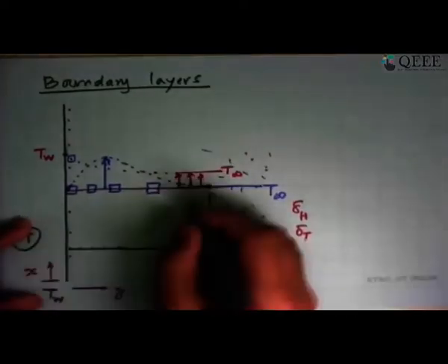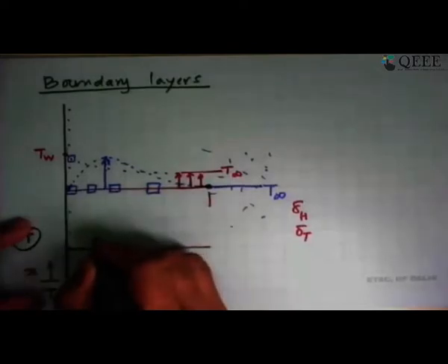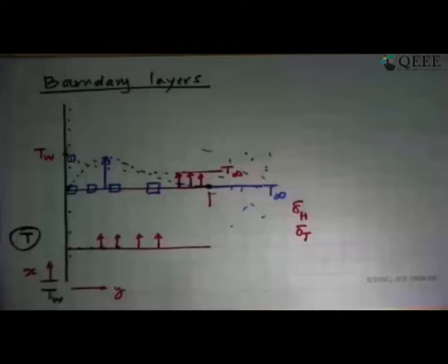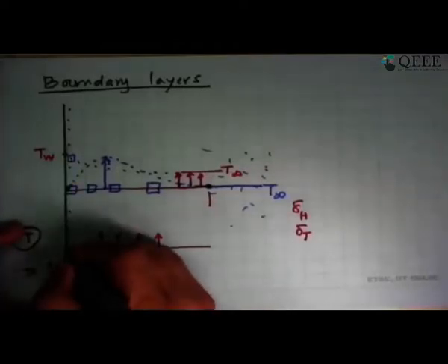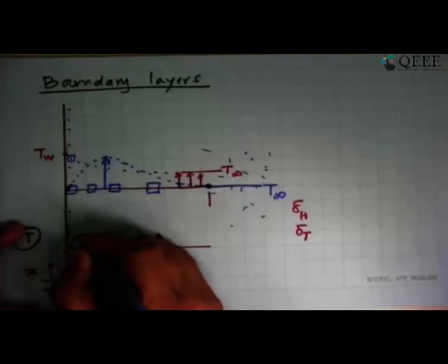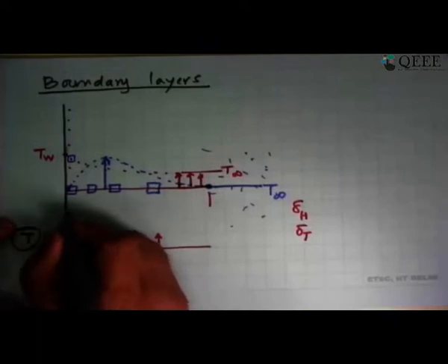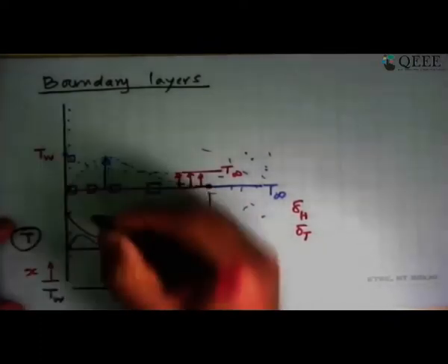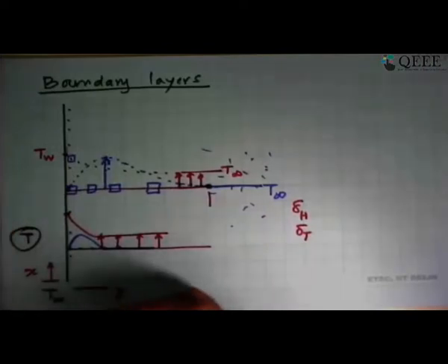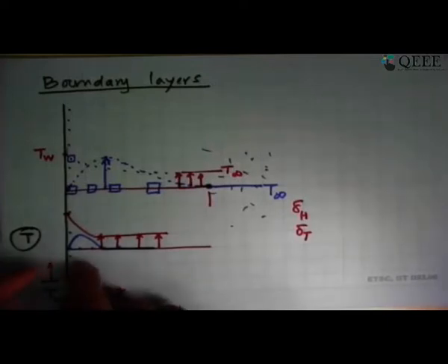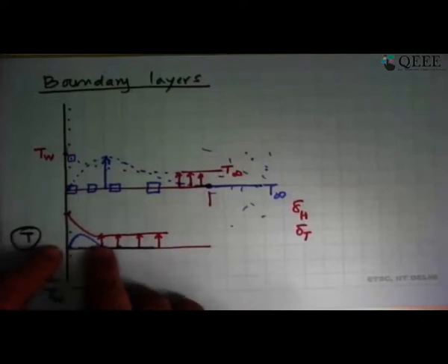If you come further down closer to this, maybe the temperature difference here did not go very far, because the flow was now, as we see, going to take place upwards in this direction, and so the temperature profile here is going to be, the velocity profile will be something like this, and the temperature profile here, the TW, will be the same thing we had earlier, but now the temperature will drop much more sharply and then become constant. So this is what is happening, that away from the plate, the temperature keeps decreasing.